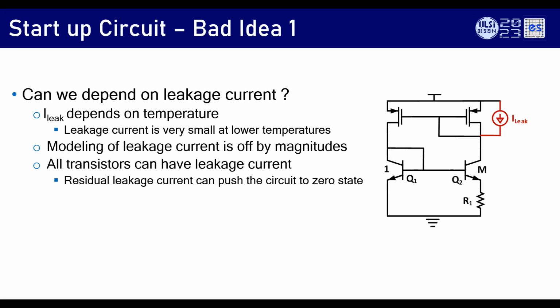That's also possible. And third is the modeling of the leakages. I don't know how accurate it is in these technologies. I've seen orders of magnitude of at least 10x. You say that simulation leakage is 1 picoampere, in reality it may be 10 picoampere. It's possible. So don't do this. Basic idea is: don't rely on leakages for startup. You design a startup by yourself.